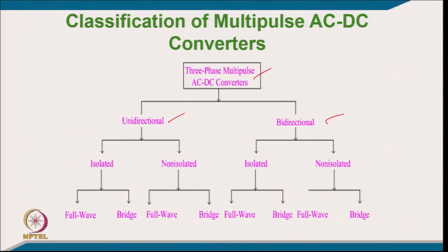So, in many applications which are unidirectional power flow, like process industry, like your electroplating plant, electromining plant, people are replacing the thyristor with the diode and then using a single IGBT, even up to 3 kiloampere or 5 kiloampere order, like they are available now. It does not require DC control for very high frequency, order of 3 kilohertz is reasonably well. So, there are plenty of changes.